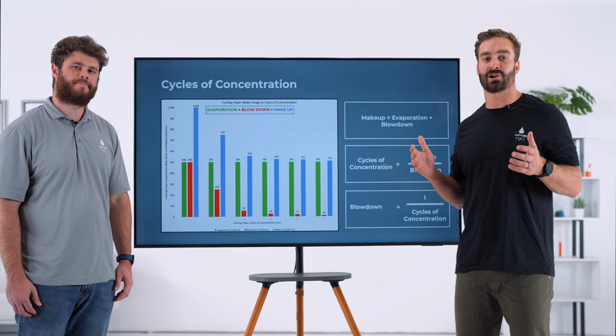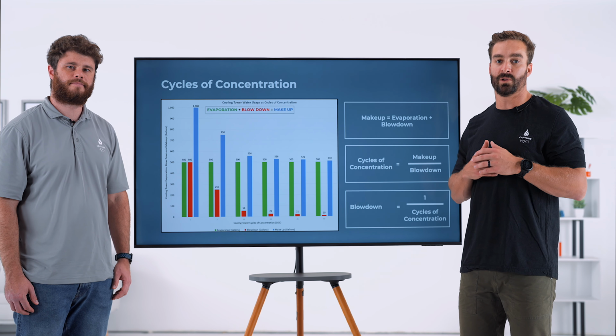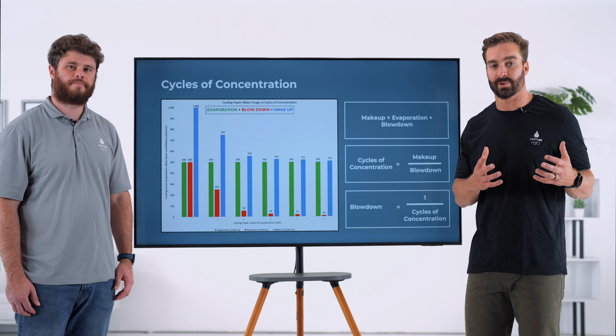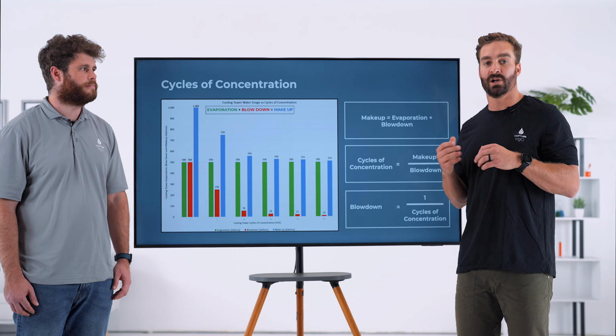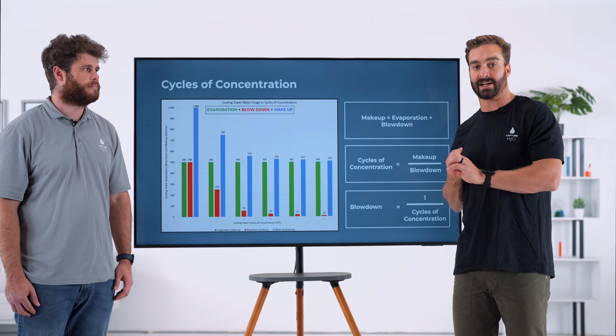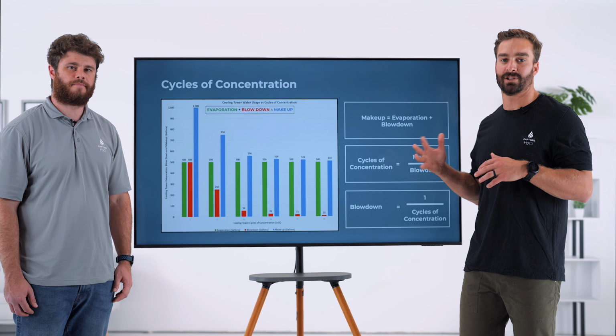All right, so how do we determine how many cycles of concentration we can run in your system? Well, the way that we do it with a chemical water treatment program is we use a term called Langelier Saturation Index, or LSI. LSI allows us to figure out at which maximum cycles of concentration we will be protected from scale, corrosion and bacteria, and our chemical half-life will be effective. If we're running the high cycle program or the hybrid program at your site, our cycles of concentration are limited by different factors, and we'll talk about that in a later session.